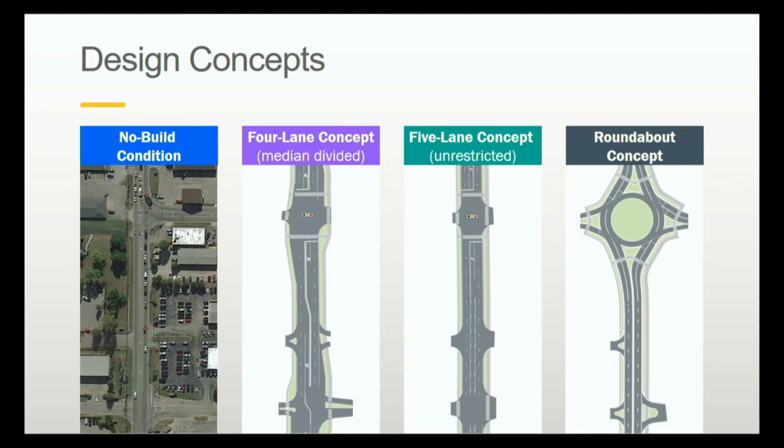So we had a rough estimate of right-of-way acquisition for the actual roadway itself, but we held off on talking about that because we had not done enough detailed design to show tie-ins for grading and that sort of thing, because we knew there were going to be wider construction easements, and we didn't want to show one line and then come back and have the line be further out.